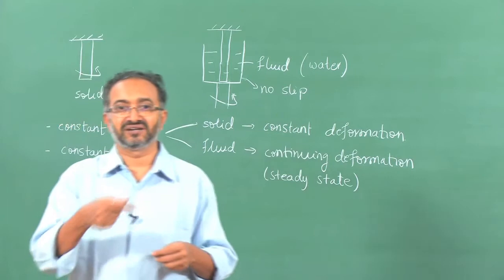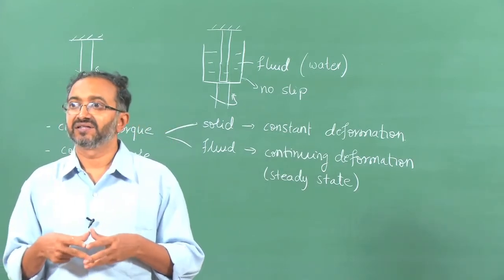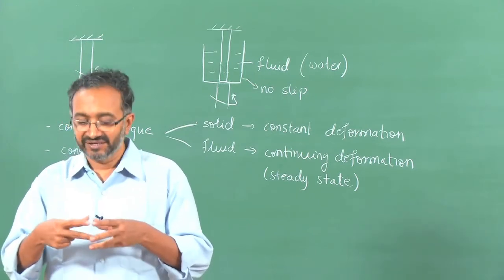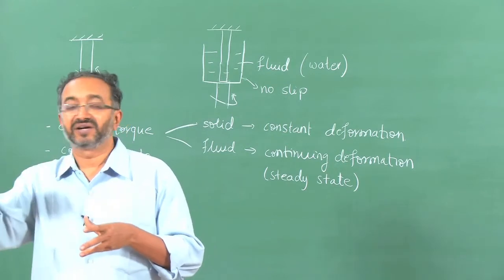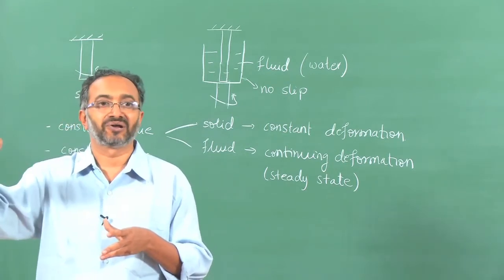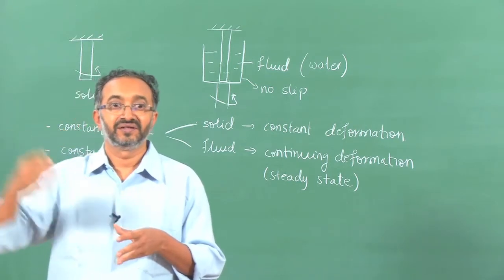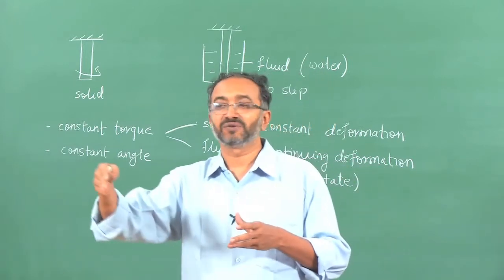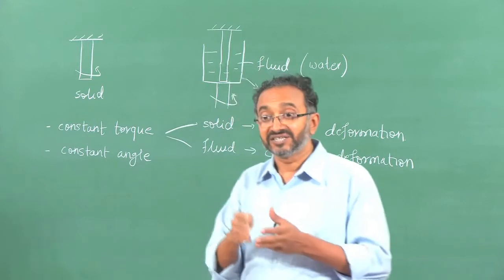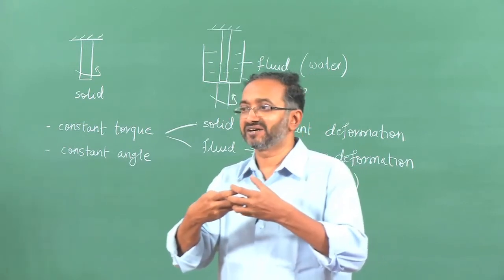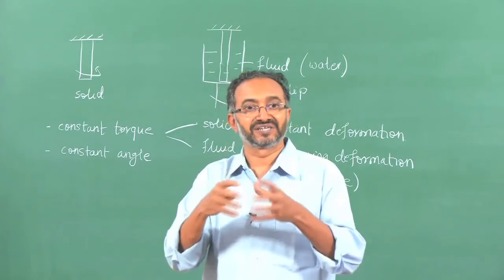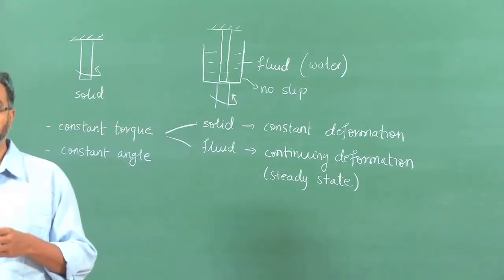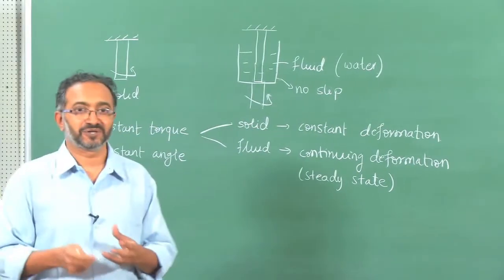Depending on the structure, for example, it may be that there is a little bit of flexibility in the colloidal flocs and therefore some flow is there, but then the particles get locked, and then we will say that this material is a gel and it does not flow at all, it gives a solid-like character. The reverse possibility is also there, that the flocs are there and then they break, so the material starts flowing like a fluid. But initially you may have a jump in deformation, because initially the particles respond as if they are atoms in an elastic network. So you will have a sudden deformation and then it will achieve a fluid-like state. Therefore both of these combinations are possible.